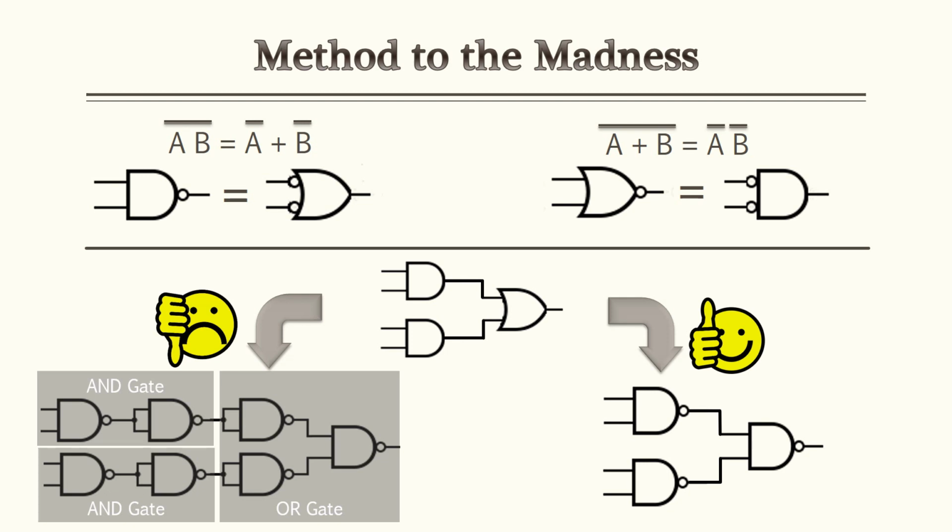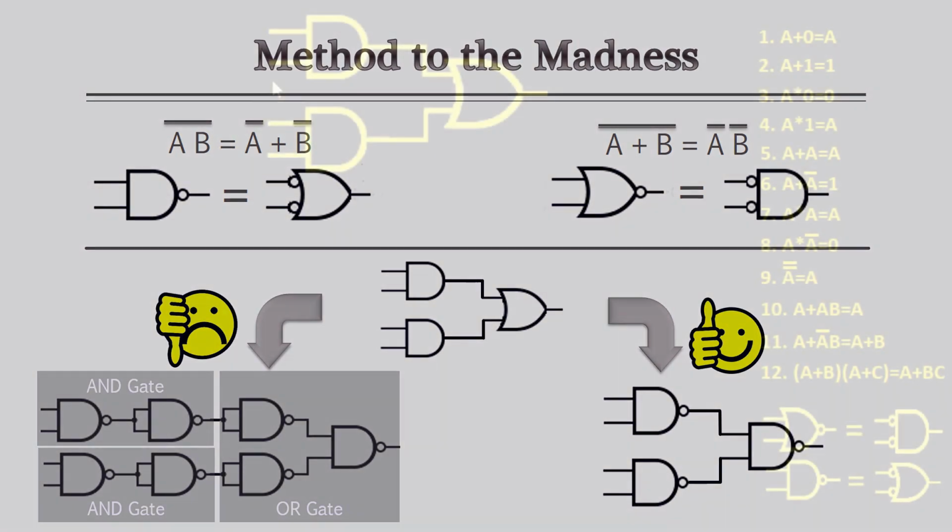Well, we're going to use a bubble method to create an ideal circuit which requires the least amount of gates. The bubble method is similar to the methods you see at the very top here. We have a NAND gate, which equals a negative OR gate, and a NOR gate that equals a negative AND gate. And we'll go over later on in the examples how to do this bubble method. If you understand how to do this bubble method, you'll create a circuit with the least amount of gates, and it'll be an equivalent circuit using a universal gate system.